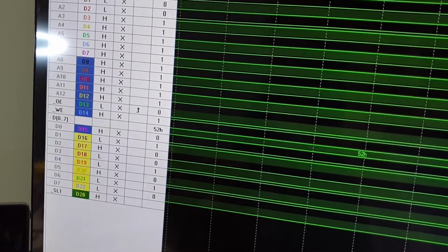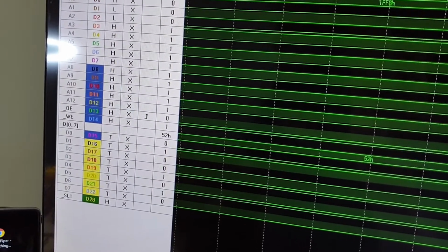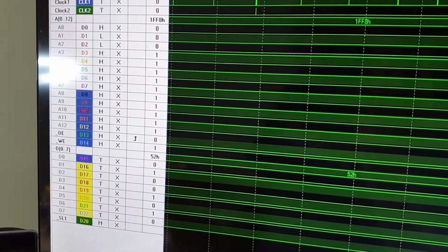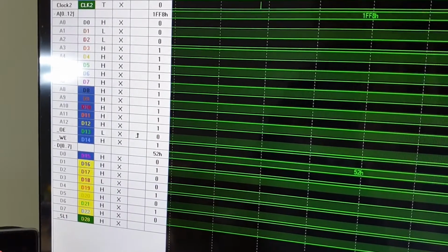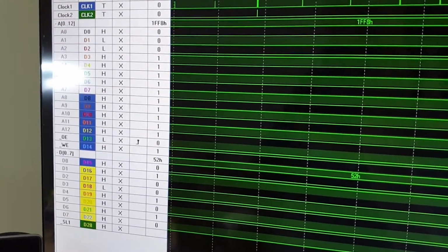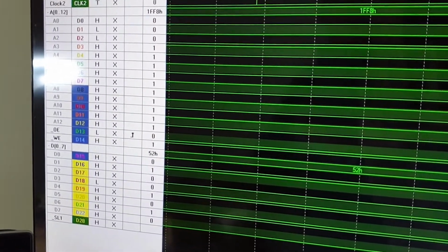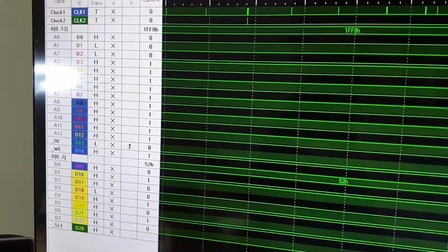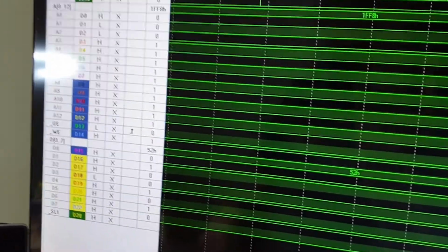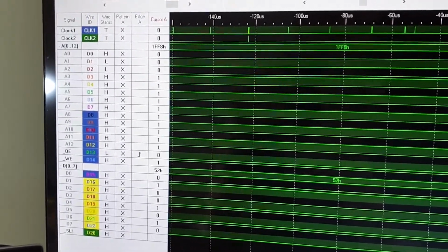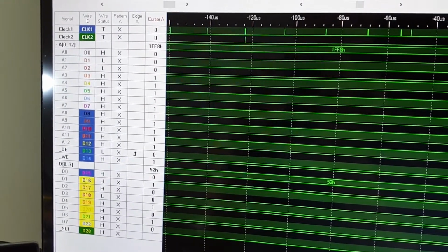So now I set the extended memory bus to be high. I do a write enable. Again, high, low, high, or 1FF9 this time. Good. Write enable disabled, and then disable the extended memory bus again. And now it's come back to output enable mode, with 1FF9, and the internal memory address is high, high, high, low, high, high, high, high, which is the memory that we had just written using the second 1FF9 memory address. So that proves that our memory for that bit plane RAM anyway is working correctly and as expected, and all of the bus logic is working as expected so far, which is really good news.